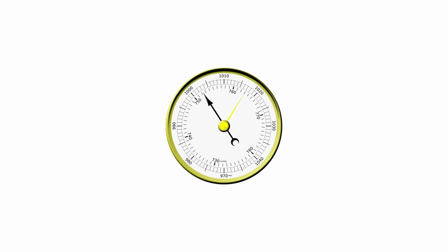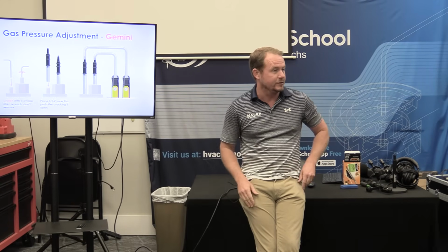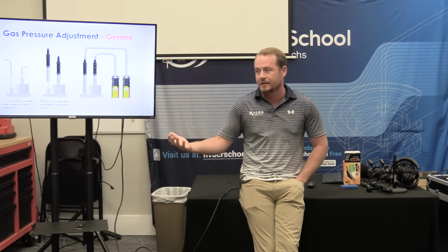If you look at the weather, it shows barometric pressure and how that changes. So pressures are always changing, even at sea level. If you went to a different elevation, the pressure would obviously change. But pressure changes regardless. It can change because wind is blowing on one side of the home, which can pressurize particular rooms or spaces. Those things can impact a pressure measurement, and you have to have that true zeroing.